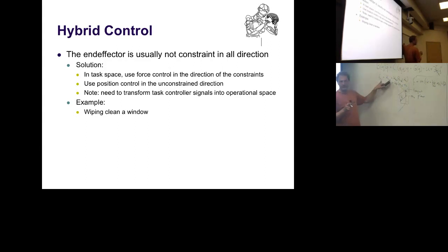Okay, so that creates the force in those directions. The same would be in the T2 direction, and in the normal direction we use this force controller. And then we run this three-dimensional force vector through the Jacobian transpose and get it back down. It looks a little complicated, but actually it's very trivial. We just have our good old friend, a PD controller, now in end effector space, and we have a special force control law in tangent space.